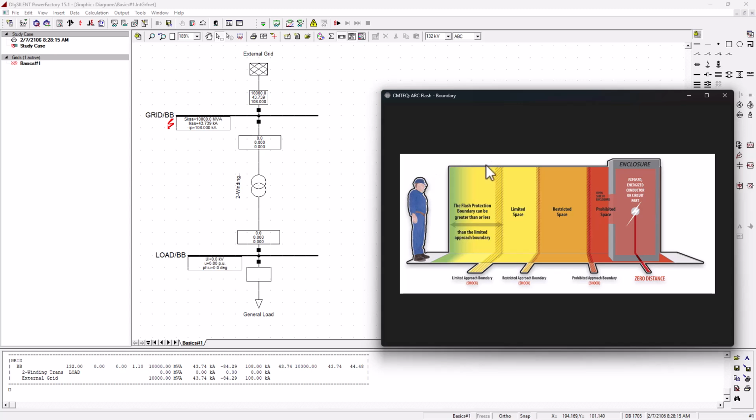We also need to know when it's safe to re-energize switch gears after maintenance or after a failure, whether you can safely close the circuit breaker again to allow power to circulate, and the safe distance that workers can operate. So protection, coordination, there is a lot of things that these arc flash analysis can inform us in terms of ensuring that there is reliability and continuity of supplies as one of the main requirements of power systems protection.